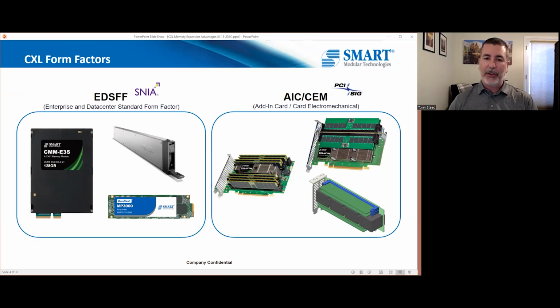The other form factor that's emerging currently is the add-in card form factor, sometimes referred to as CEM, card electromechanical. There are a number of different ones becoming available. Smart has introduced some as well, but those are the standard add-in card that you would see for a graphics card or a NIC, those types of devices that have been in use for a long time.